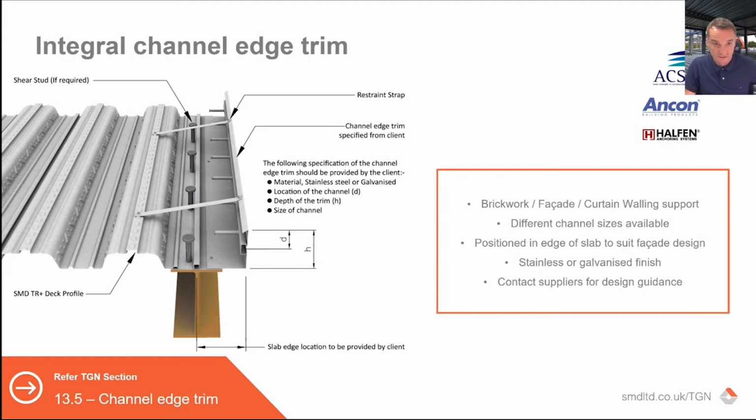This is more just to indicate things we also offer. We also do offer channel edge trim. We don't manufacture it ourselves. We use a number of approved suppliers, and we would detail and supply that. The edge limits are slightly different, and that's largely due to the weight in the channel, but that's obviously all guidance, and it does vary from supplier to supplier, but it's something we will look at in our design and then determine whether any edges would need propping to those edge trims.